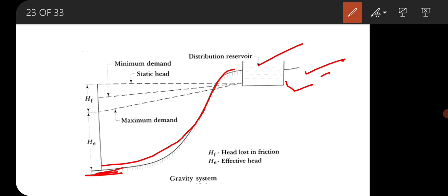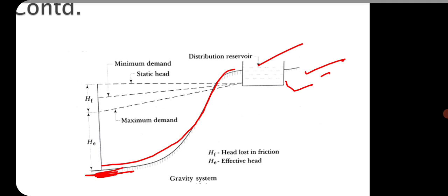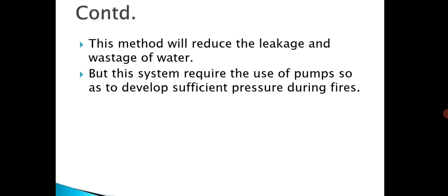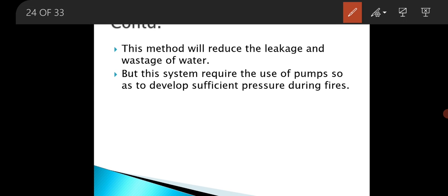But after the treatment of water, it will be distributed to the low leveled consumers situated at the foothill by mere gravity. Hence, no pumping will be required in the distribution system. This method also reduces the leakage and wastage of water.